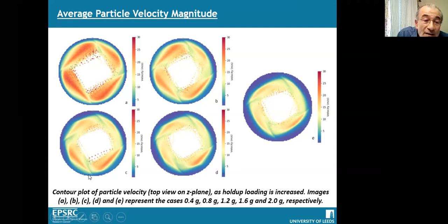The jet, which is around here, actually projects the particles out of the bed surface and impacts them in this region. So near the bed surface, there is a lot of collisions at high velocity, and that goes on in the whole system around for all the jets.